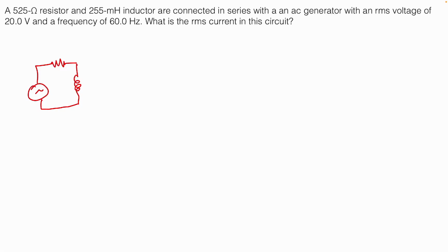What do you want to go for first? Turn the inductor into a resistor so that we know what we're doing. Okay, I like it. It's omega times L. I know this omega is 377. How do I know this omega is 377 without even looking? It's at 60 hertz. The United States uses 60 hertz. So whenever you're using mains power, the stuff that comes out of the wall, the 120 volts, it's in the United States at 60 hertz.